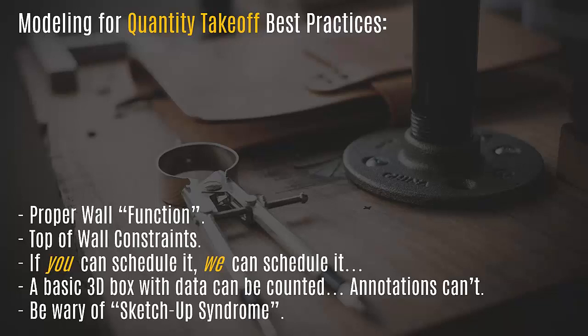And finally, be wary of what I call SketchUp syndrome. I'll give a quick example of that too. But essentially, it's creating in-place masses or in-place extrusions. The reason they are dangerous is that their quantities and areas are usually taken off inaccurately.